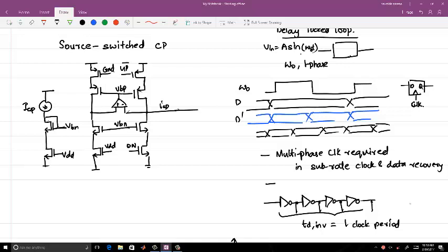Whereas for 10 Gbps, I think for all the RF requirements, even for 2.4 GHz or even 0.9 GHz, you go for LC, which has lesser tones, and it's very important to look at the spurious tones in case of RF applications. So ring oscillator based delay lock loop, ring oscillator based multiplying delay lock loop, fractional-N, and all these things will be pretty common in broadband, but may not be that common in high speed RF applications.